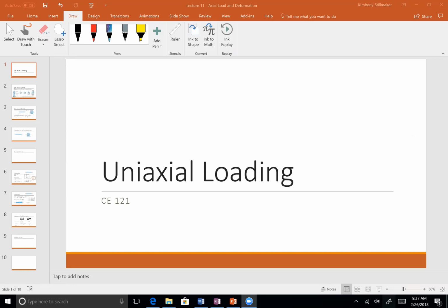We've talked generally about the stress state acting on an element, how it can have those 9 unique stress components. Each of these types of geometries and loadings are going to correspond to certain combinations of those 9 components, where many of them will be 0 and others will have a non-zero value. I want you to always keep in mind that there's a bigger picture, a more general concept: we could have any 9 stress components acting on a material element and we know what to do with it. Whereas this is just giving us very distinct cases that are common in our experience as engineers.